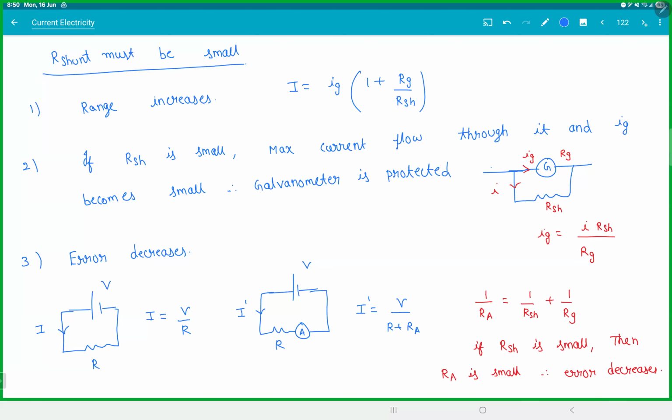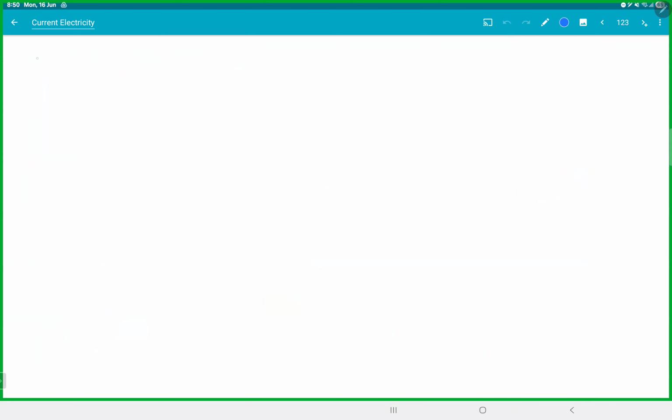Clear? Next thing, voltmeter. So you want to measure voltage. And again, remember the story, the only device you have is the galvanometer. There is no other device that we have. So it measures voltage, and is constructed by keeping a large resistance in series.